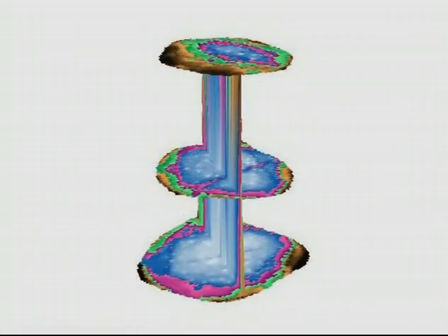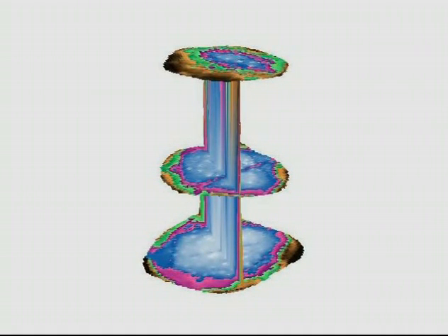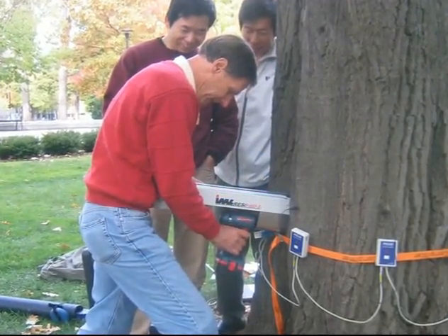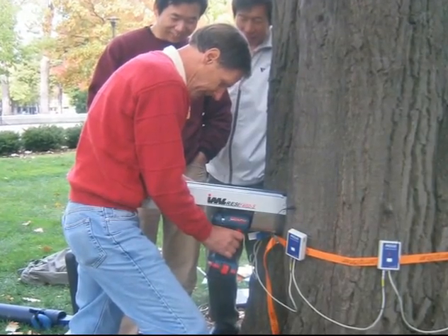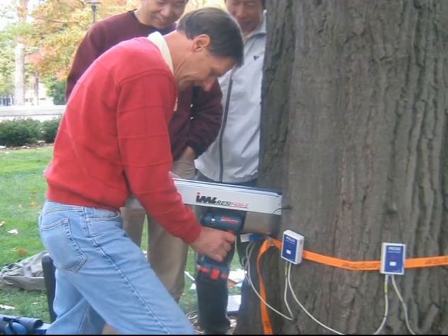Tomography software is able to combine the 3 tomograms, creating a 3D representation of the study area on the trunk. Resistograph tests were required to verify the exact type and extent of the suspected defects and decay indicated on tomograms. The value of tomograms in those cases was that they identified the best location for drilling, significantly reducing the number of drills required and enhancing the value of the data acquired.